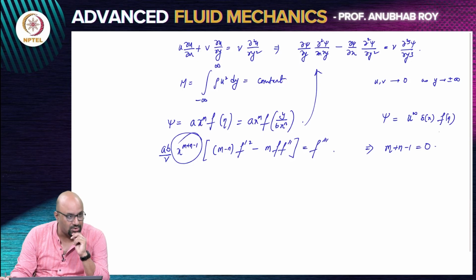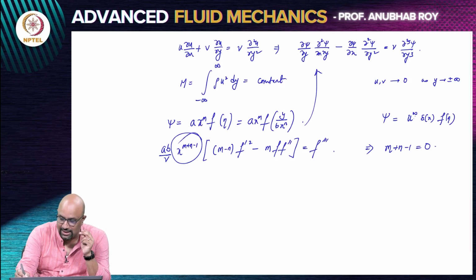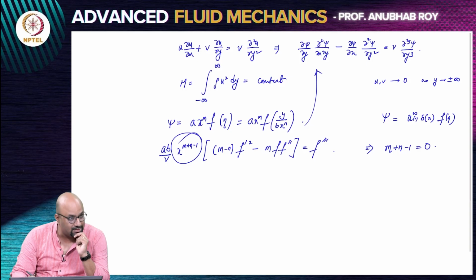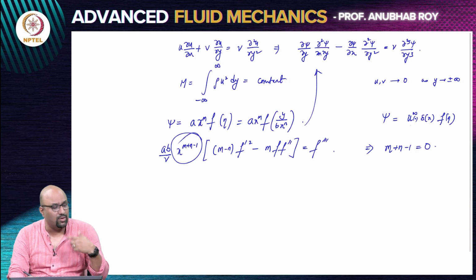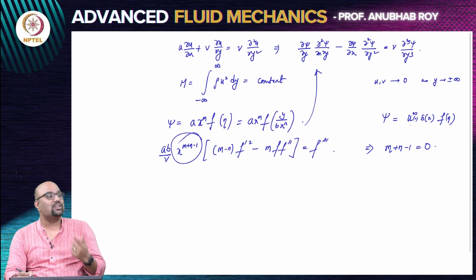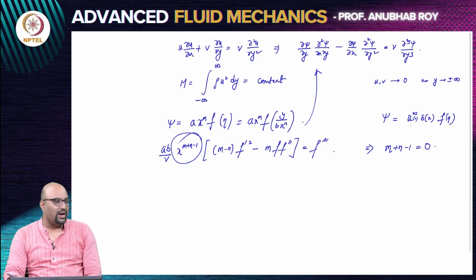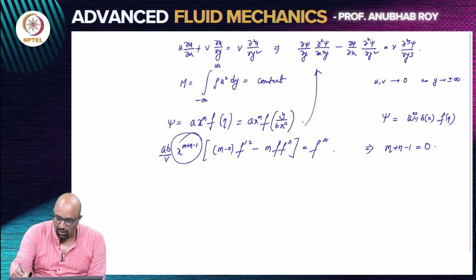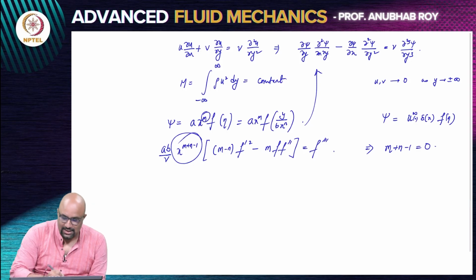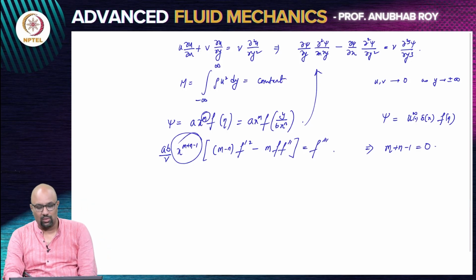This is what ψ was, and then when we did Falkner-Skan, we also allowed this to be a function of x. In the Blasius problem, we worked out the differential equation for δ of x, and then we got that δ of x went as root x. And when u of infinity was a constant, that means m was, what was m in Blasius?